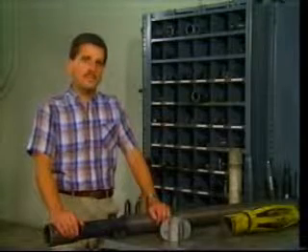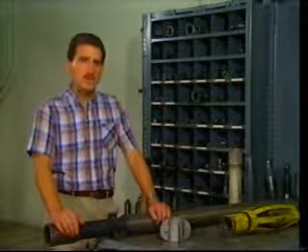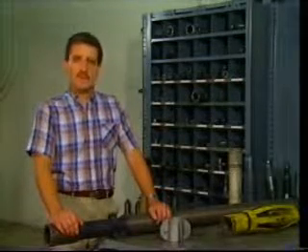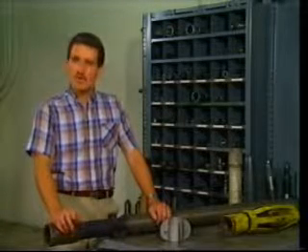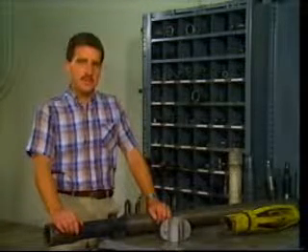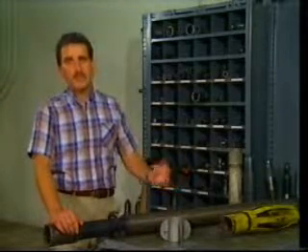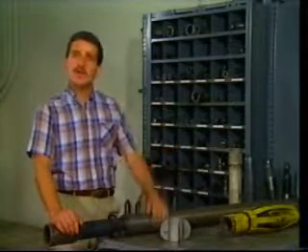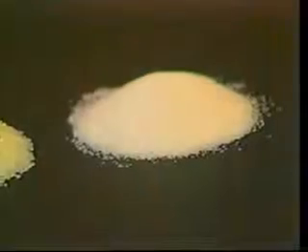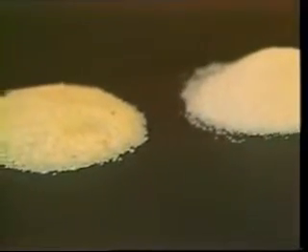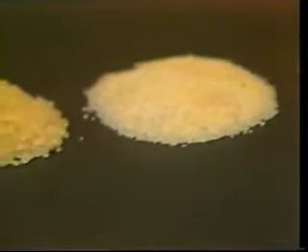Due to improved methods of squeeze packing and perforating, the internal gravel pack is the most widely employed technique. Overall, a properly executed internal gravel pack offers greater flexibility, selectivity, planning time, and reduced rig time and cost than other methods. In any gravel pack design, the gravel size is crucial.